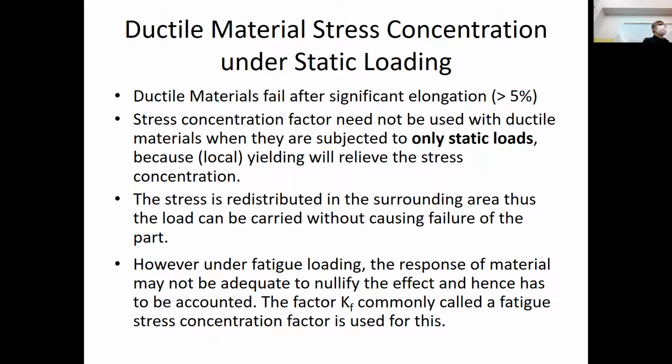However, if your part is made of ductile material but your part is experiencing fluctuating loading that can lead to fatigue, I have to include a stress concentration effect. And in this case, I'm not going to be using KT. No, I'm sorry. I will be using KT to calculate a KF. So in my stress equation, I will be looking at a fatigue concentration factor. And I'm going to talk more about it when I get to fatigue.